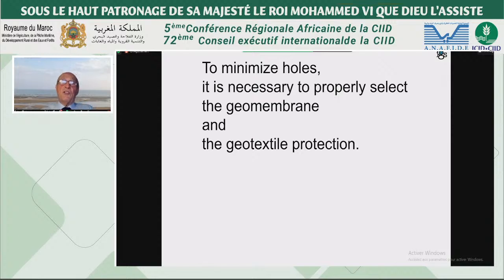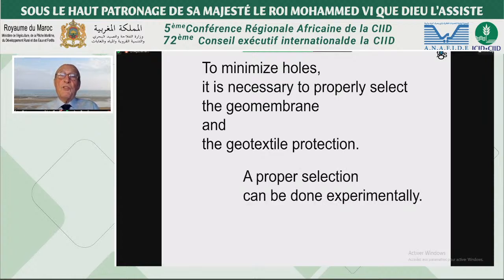To minimize holes, it is necessary to properly select the geomembrane and the geotextile protection for proper resistance to puncturing.